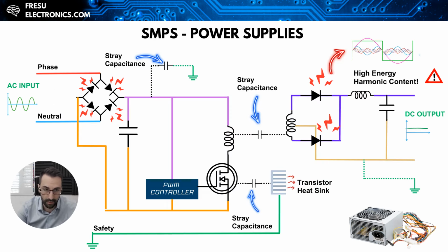The next issue we need to cover is related to the source of noise caused by the rectifier used during the rectification process. Different types of diodes can be used for rectification. However, the ones subject to more EMI issues are the fast recovery diodes. Fast recovery diodes are preferred by designers as they improve the efficiency of the power supply, but typically these choices result in more issues in the EMI realm. And as usual, this imposes a trade-off between power losses and EMI performance.